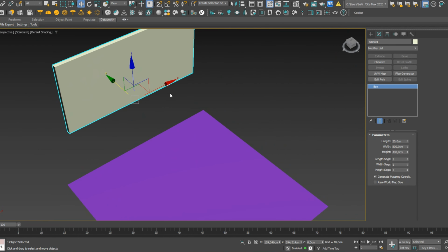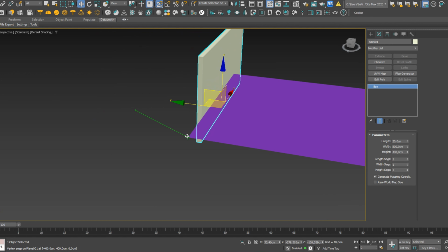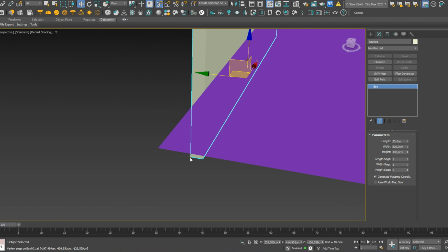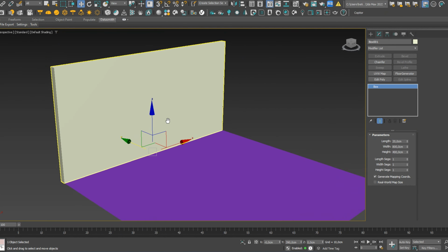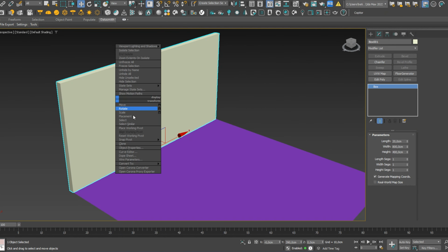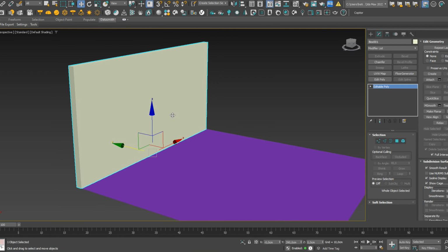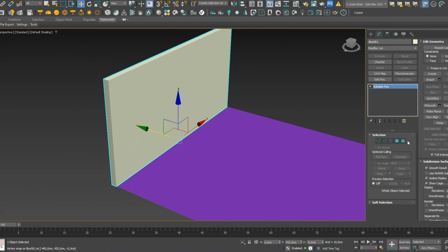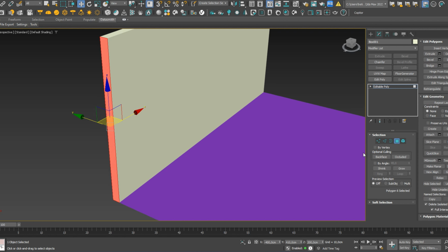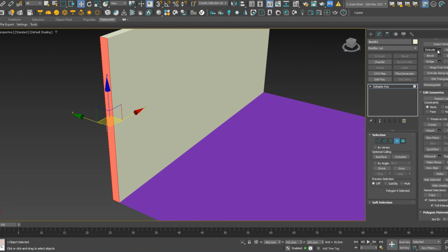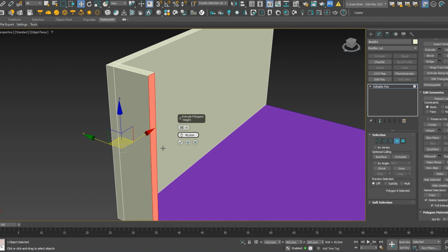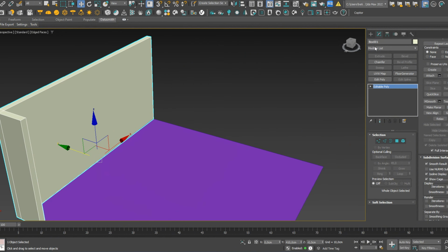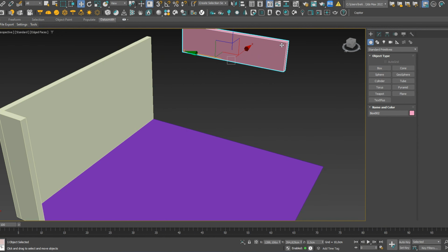While placing the box on the plane, I used the snap tool above. Shortcut is S. Next, I convert this to an editable poly. Here, I applied an extrude of 20 cm. Then I applied 90 cm extrusion to draw the side wall.